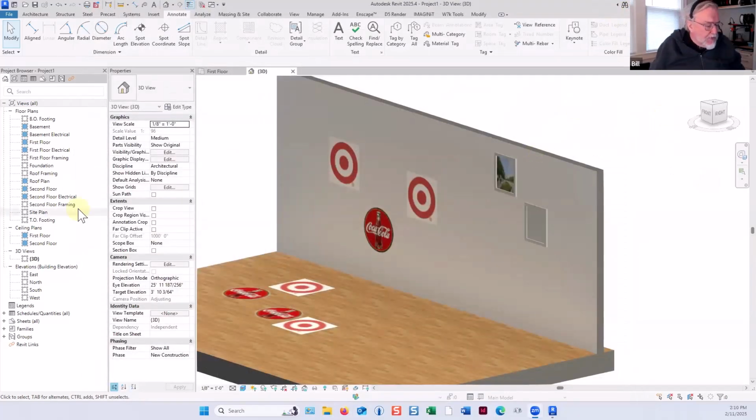What I would like to do is on the last page here, exercise number 2. Number 1 was making the picture frame. Create a new family for a brushed aluminum stereo system amplifier, 17 inches wide and 15 inches deep and 5.5 inches high with black 1/2 inch high legs.